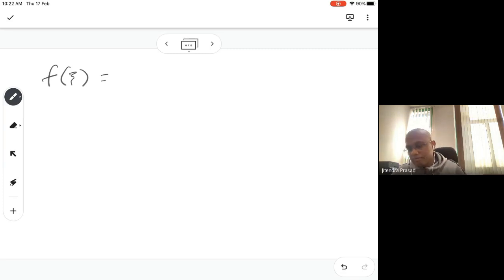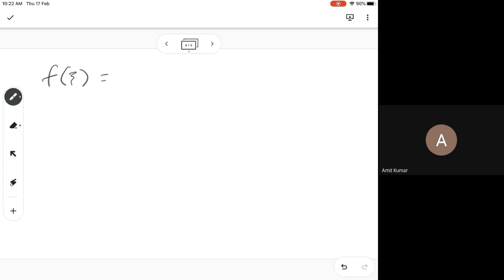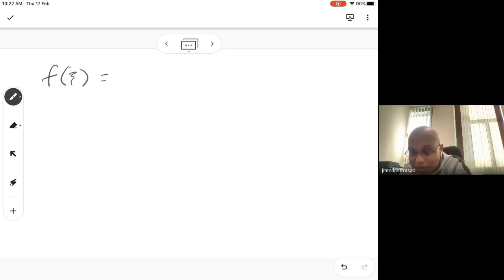Only one point. We have to extend it to multiple points. There is a concept in finite element software, when you work, where integration point things will be coming up somewhere in some document. So this is what we're talking about. There may be some kinds of elements which are called reduced integration, which really means it is not calculating exactly. So this kind of thing comes from that.